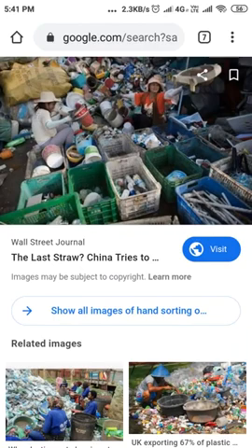In this, the most common method is the recovering of the ferrous scraps. By shredding the solid waste and using the magnets, you can recover the scraps. These ferrous materials are recovered either by shredding, or before the air classifying, or after the shredding, the air classification. In some of the larger installations, overhead magnet systems have been used.